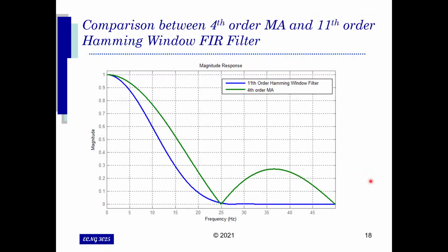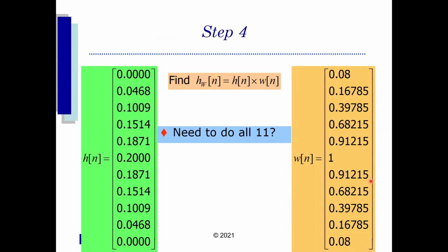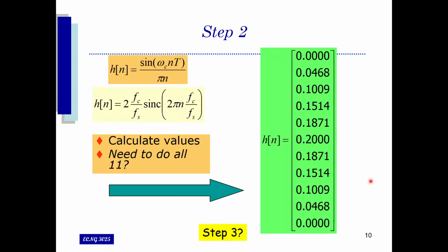Alright, so typically that's the type of question that you will get regarding how to go about doing a FIR filter design if you encounter these questions in your final exam. We basically will be given the cutoff frequency and the sampling frequency, and then it will tell you to design for the moving average filter accordingly, and to design the FIR filter using a windowing function, and they will give you the equation for the window function. What they will not give you, and I'm backtracking here, is the h of n equation.